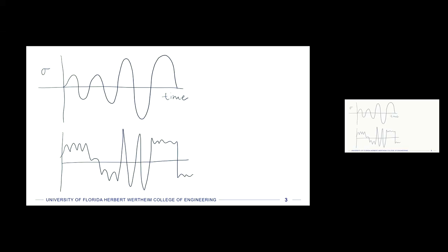For example, aircraft going through different airstreams. We can't predict the local fluctuations in those airstreams, just how they generally change. So this might be a measurement where you have a segment here with a mean stress that's greater than 0. You could have a mean stress that's 0, or you could have regions down here where the mean stress is less than 0.